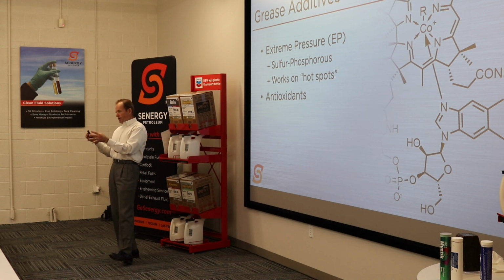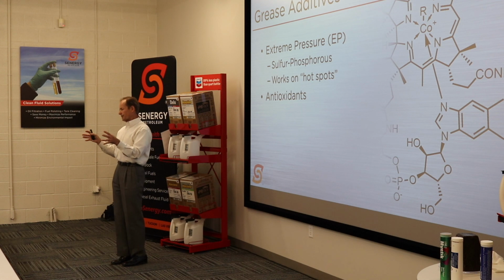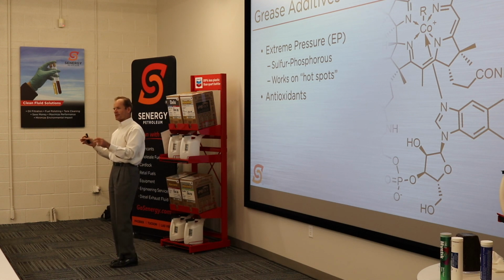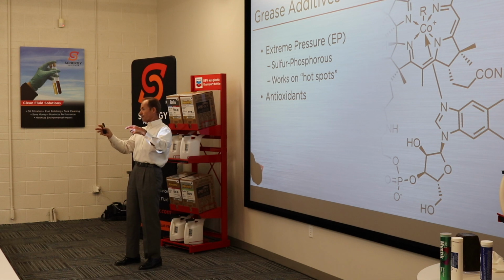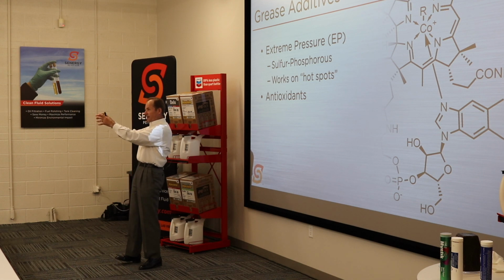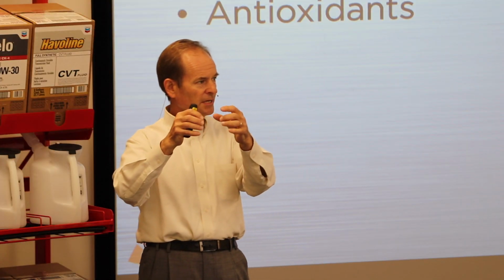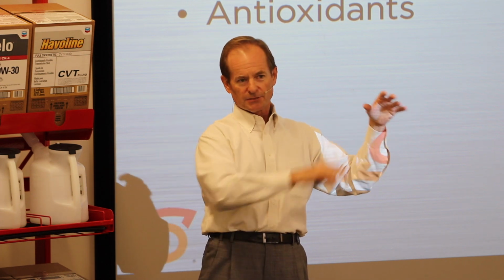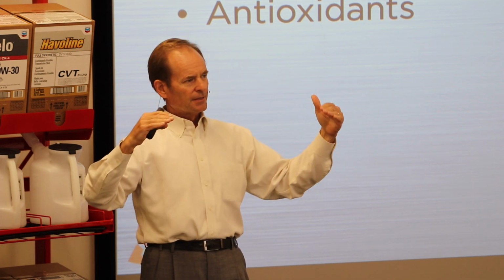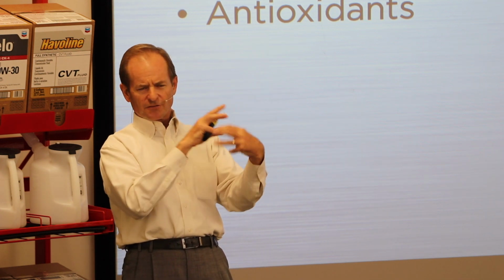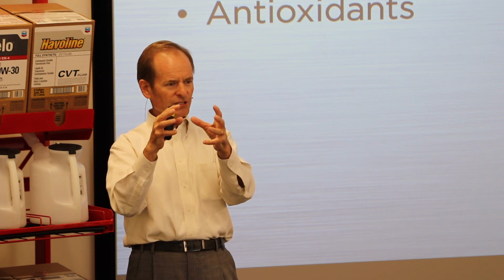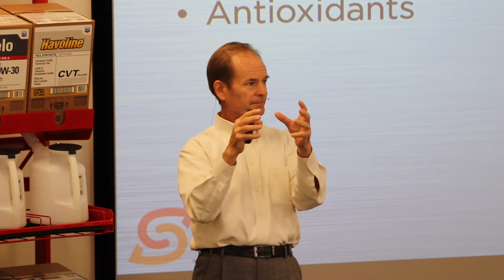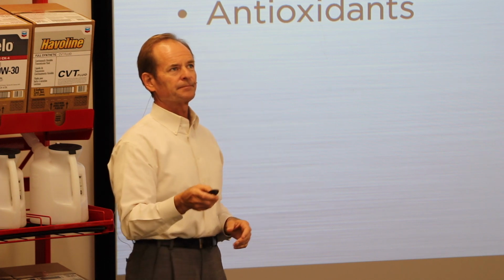Unfortunately, unlike oil, let's see if I can make this point any better in this session than I did in the first session. If you've got a bulk of oil in an oil system and you happen to get a hot spot here, use up some of your antioxidants to fight the oxidation, but you know, you've got all these additives throughout the rest of the oil. So your overall level, it gets mixed around, your overall level of antioxidant doesn't go down very much. In grease, because grease doesn't mix and flow with each other, if you used up a bunch of antioxidants in one part of your grease, they get used up. You're not replenishing anything.